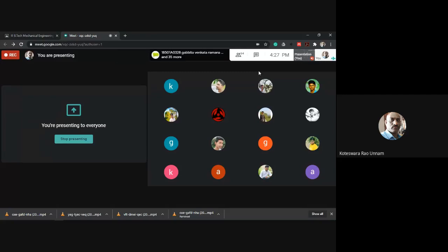Okay. So similarly, if we go to the next page, he has given two different types of riveting, that is chain riveting and zigzag riveting. So he has defined the PB value. That means how much back pitch should be there per joint. Your PB should be greater than or equal to 2D in case of chain riveting, whereas in case of zigzag riveting, it should be greater than 0.33P plus 0.67D.